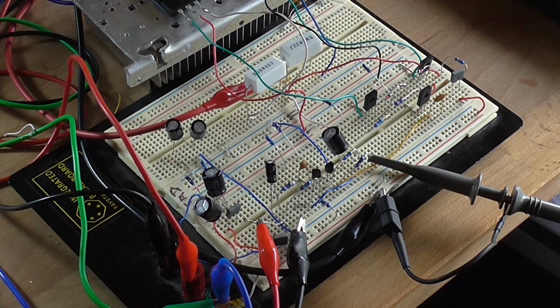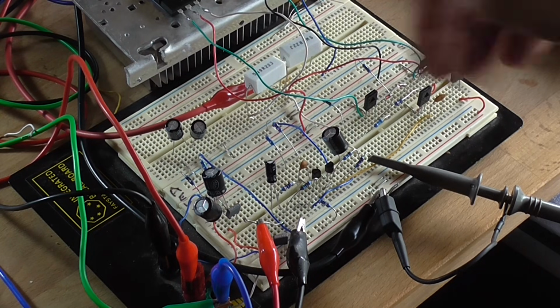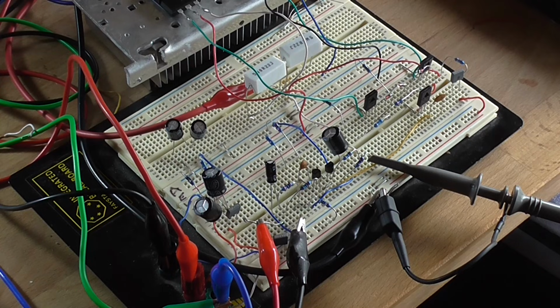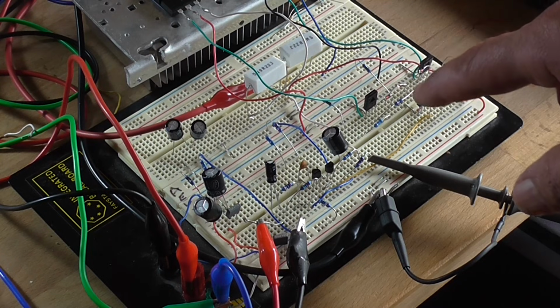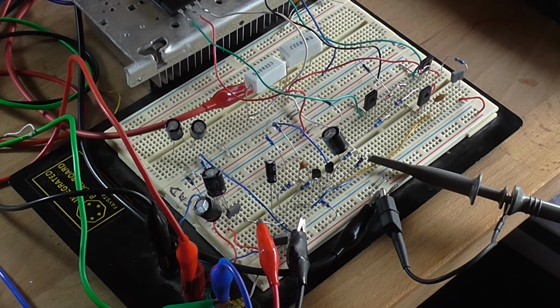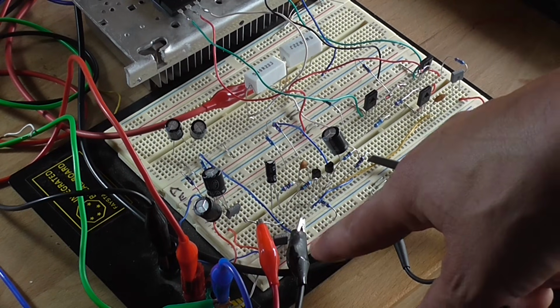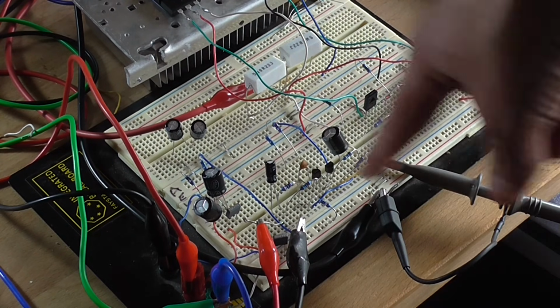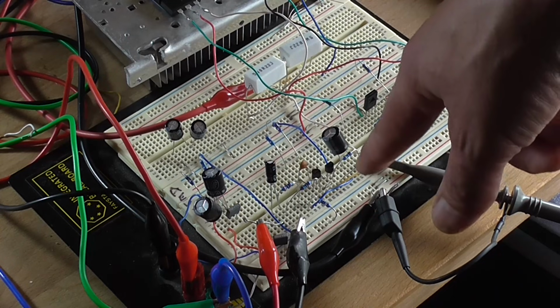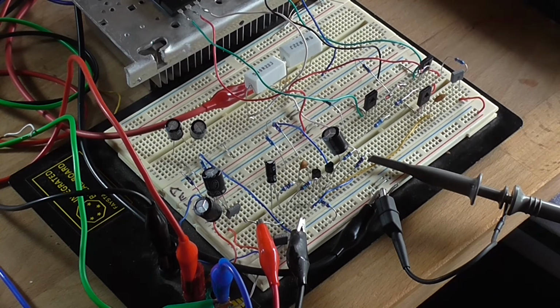Alright, all jokes aside, here's the actual circuit implemented up on the breadboard. That's just a piece of anti-static foam. That's not going to do anything. So currently I've got the power supply set at plus minus 31 volts, and all the tests on this amplifier will be done at that voltage. And I currently don't have an input signal going, but I'm measuring the output points here between here and ground on a multimeter to see what our DC offset is.